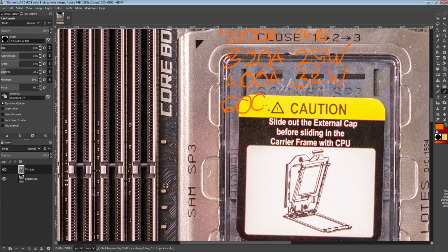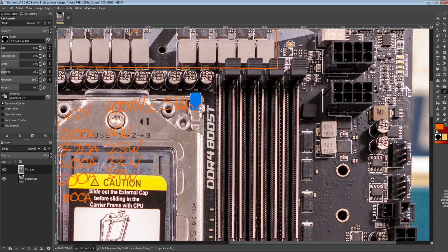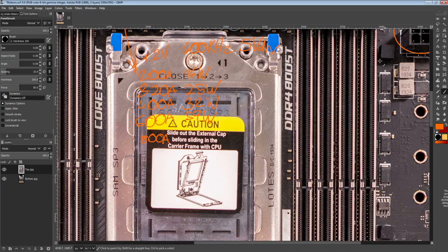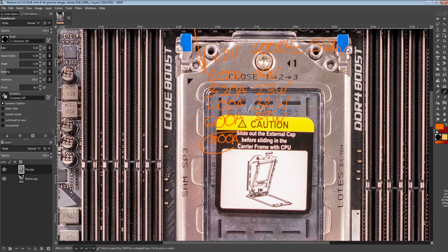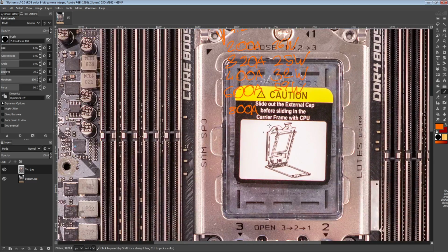Going up to 600 amps, this VRM will produce about 59 watts of heat, which depends how much airflow you cram through the heatsink, though it might still be able to do it passive. And then 800 amps, that's where theoretically the 64 core would land, which would actually exceed the power handling capability of the 8-pin power connectors. So you wouldn't want to run that long term on this motherboard just because the power connectors won't deal with it.